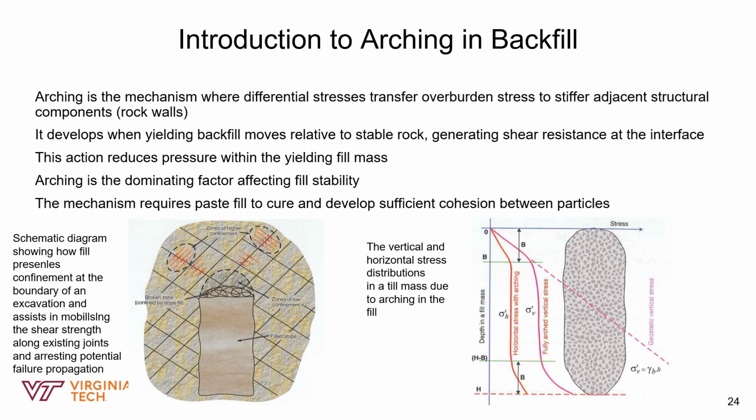So in the next few slides, we'll be looking at a concept called arching and load transfer. So what exactly is arching? Arching is just a mechanism where differential stresses will transfer the weight of the backfill onto more stiff adjacent rock walls. And this usually happens because the backfill is not a rigid block. It yields.